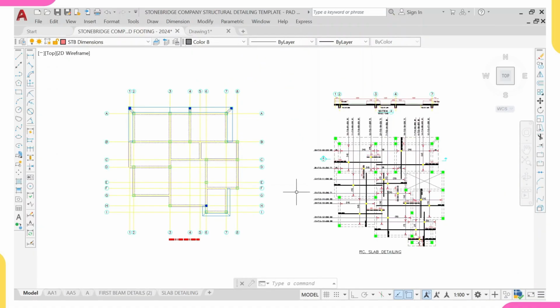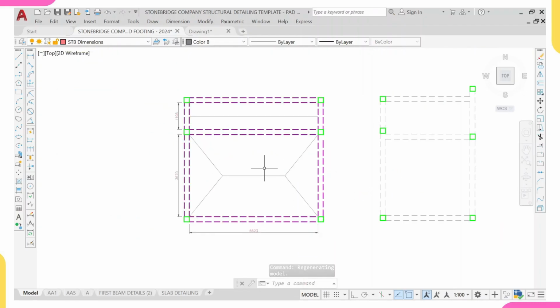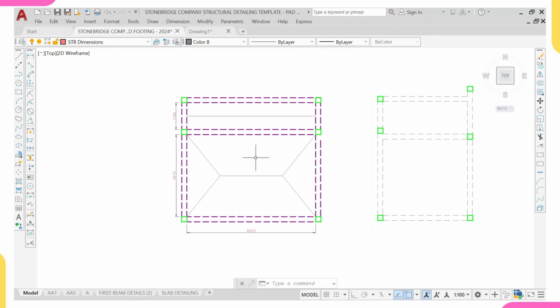I said that we have two types of solid slab, which are one-way slab and two-way slab. So coming over to this, I would like to use this to explain their load distribution, how load is distributed in one-way slab and two-way slab. In solid slab, if your LY, that is the longer span, for example, this and this, so this is the longer span, if your LY over LS, this is my LS, is greater than or equal to 2, that means it's a one-way slab.